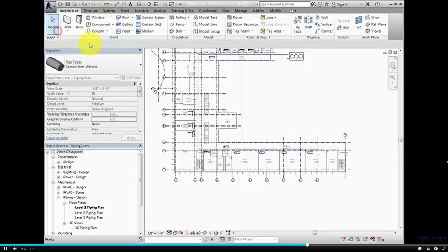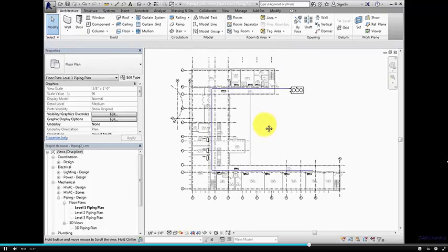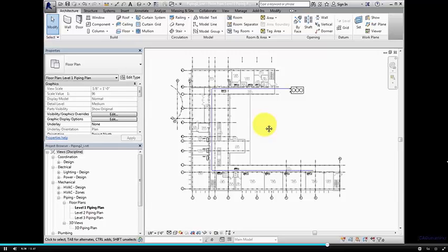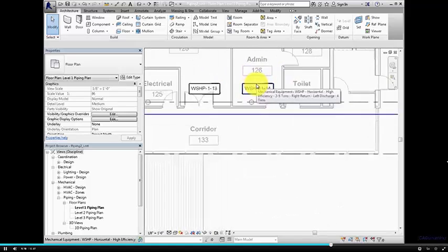For this example, you use the same pipe diameter to create the entire main supply pipe. At this point, you can size the pipe after the branches are connected. However, you could create several pipe segments along the path and change the size as you go. The next step to laying out this piping system is to connect each water source heat pump to the main pipe. Zoom out and pan up to the north side of the building.